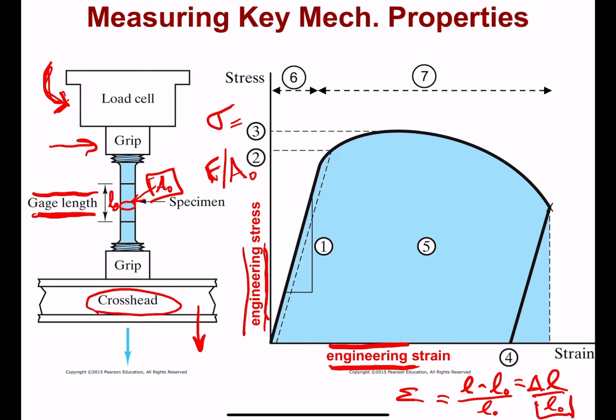Okay, so most stress strain curves are going to have a general shape where there'll be a linear portion to some limit. This might be you extending your finger to the limits you can to cause a little dimple on your knuckle. And then at some point, the material is going to start to deviate from that linear trend.